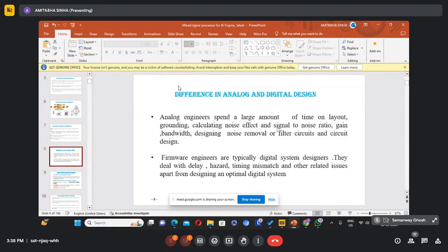So that means for a small time, both the upper input and lower input will be 1, is it not? Which is basically the delay of the NOT gate. So that means that it is called a glitch.